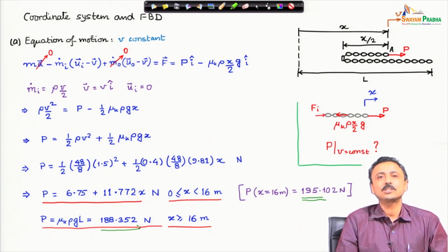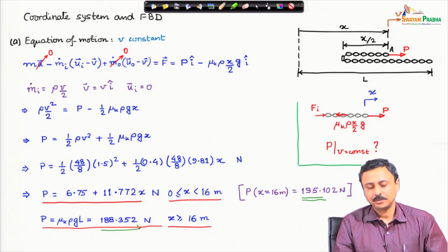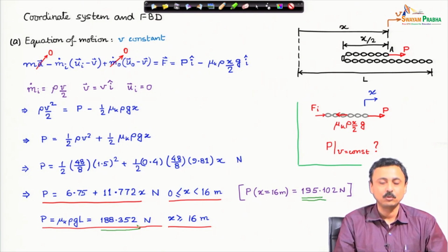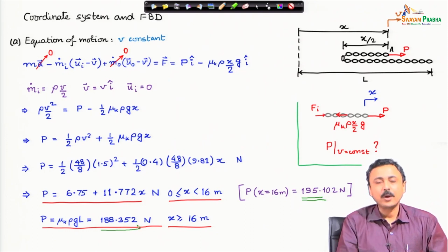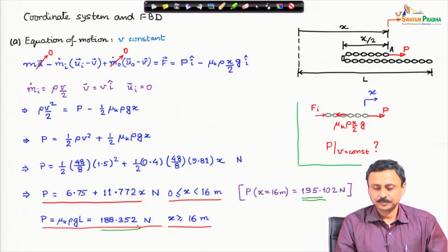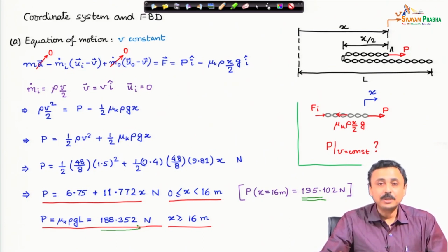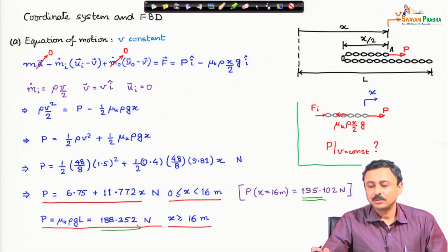It is only a constant mass system moving on a rough floor, and what we have to provide is just the friction force, and everything should be balanced because it is moving at a constant velocity. Therefore, the force required will be just the friction force. Okay, so, there will be a jump in the force requirement when the last link of the chain has been added to the system.